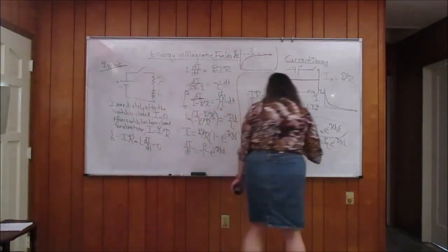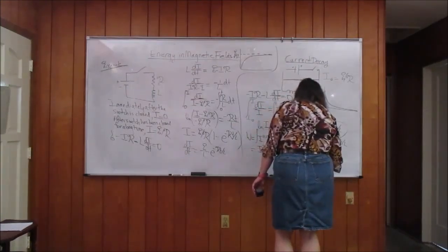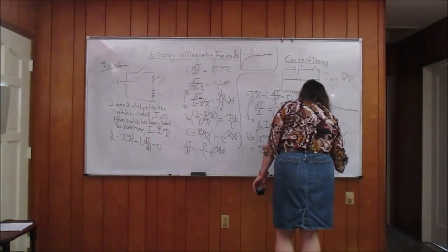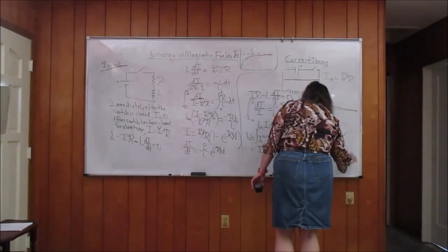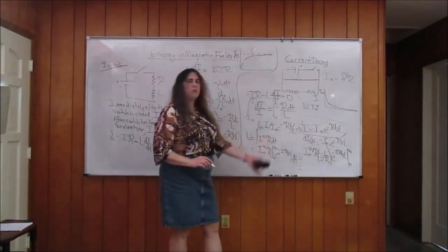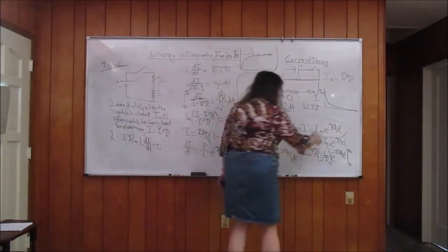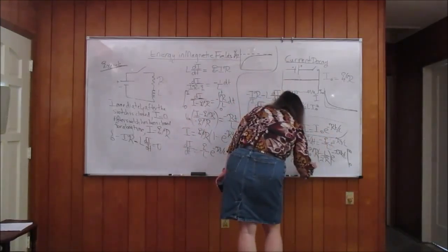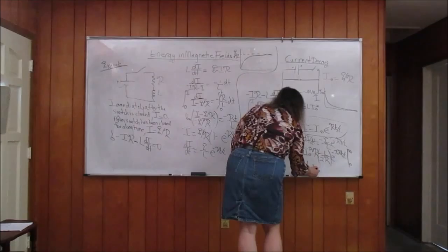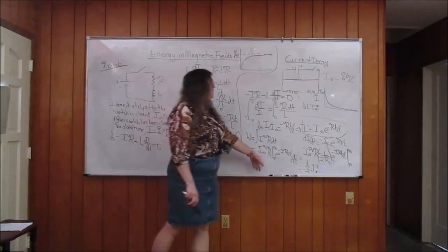Okay, so I do the math here. This is I naught squared times resistance, and I evaluate this at time equals infinity, it's equal to 0, of course. If I evaluate it at 0, this exponential is just going to give 1, so I've got minus minus, and I'll wind up with L over 2 times I naught squared. So that was the energy that's dissipated in the form of heat in the resistor.